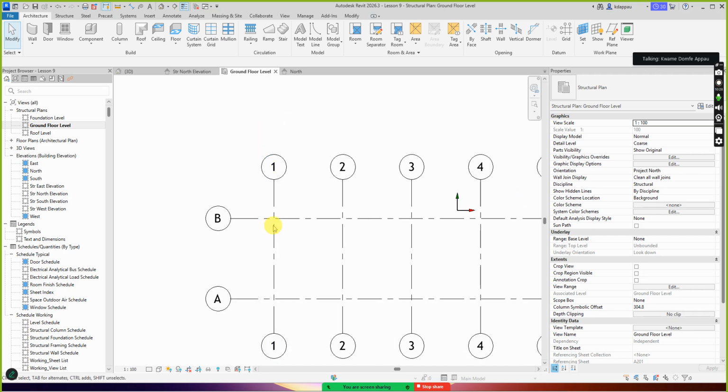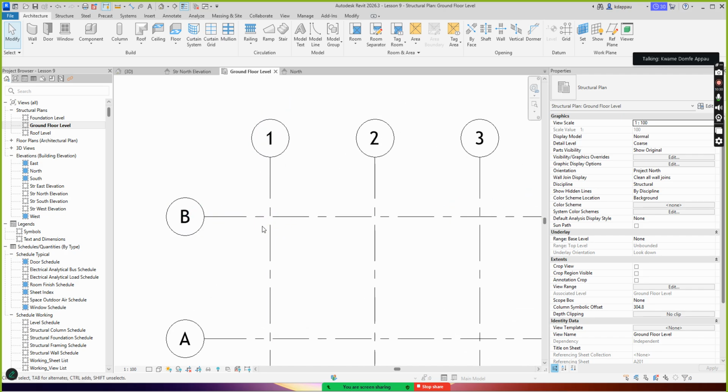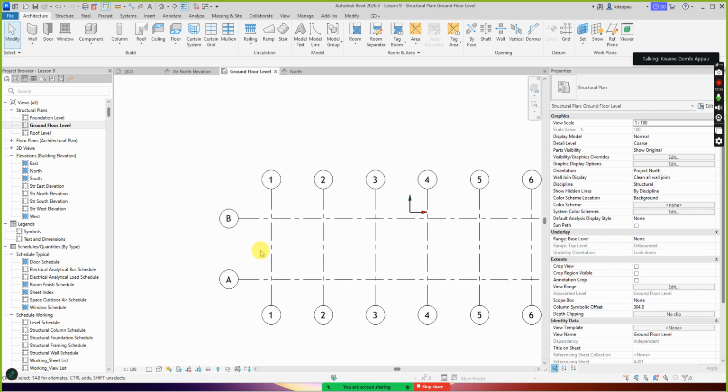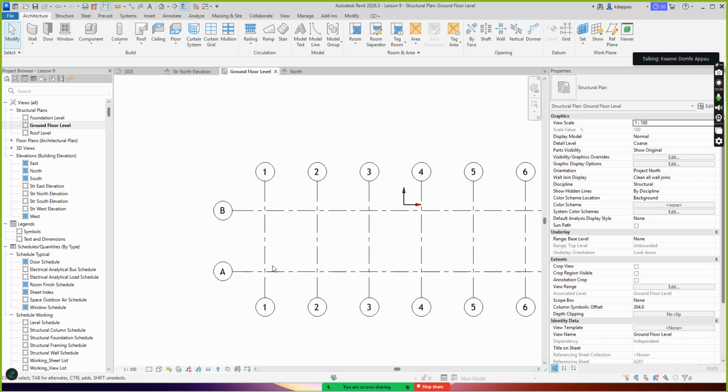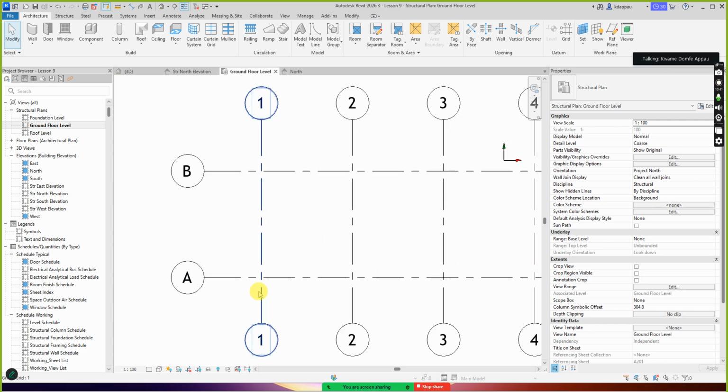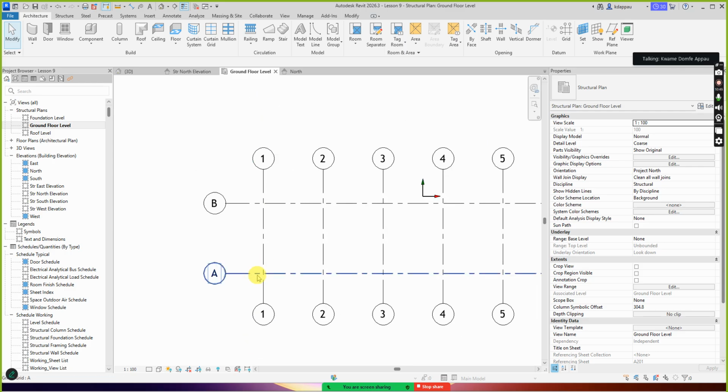Usually, a column starts from one floor and then ends at another floor. If you go to any typical construction site, you cannot erect a column that spans from the ground floor to the 8th floor. We do them piece by piece. Even if it is an isolated column that spans 4 floors and you are casting it, you cannot cast all the column for the 4 floors simultaneously.